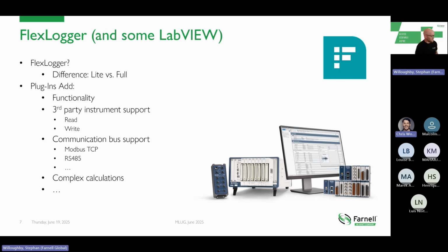Now, admittedly, if you've not seen FlexLogger at all, slight oversight on my part in that I probably should have shown you what it looks like. But I've got the laser pointer, so you can see in this picture, when you connect a DAQ up, it finds all currently connected available DAQ systems. So that could be cDAQ, USB DAQ, PXI based, the new fieldbus stuff. So long as it's a DAQmx driver, it'll pick it up. It'll show you all available modules, chassis, and all available channels within that. And then from there, it's a case of double clicking to provide that configuration into it.